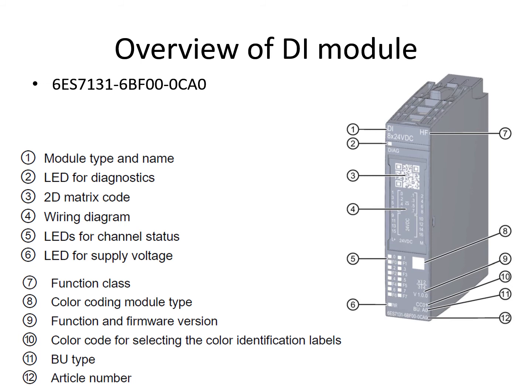First, this is a digital input or discrete input, so it only accepts digital inputs, and could be connected only to digital switches and sensors. We can just insert it on the rack, and we could add as many of these input modules to our PLC as the rack has space and room for.